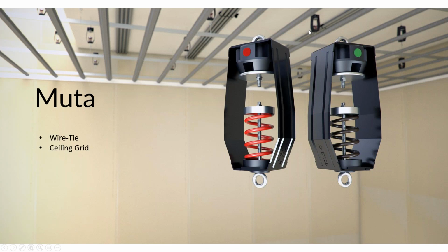The next hanger takes that same exact bracket, same coils, adds a rubber element at the top, and then 2 welded eye bolts for wire tie purposes. It's important to note that you do want to use a welded eye bolt. I would get it from Kinetics. Otherwise, it's not going to reach the overload capacity needed for code.